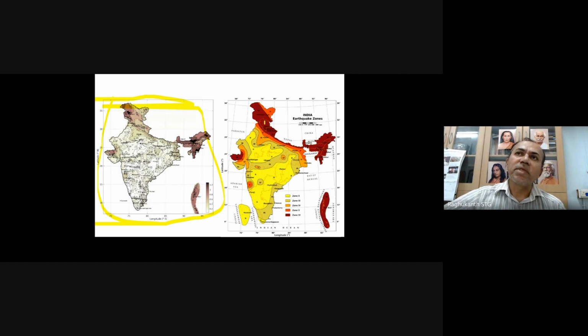Now, in the old zone maps, there used to be small islands. They were all coming from some damaging earthquake that has occurred; that island will come basically. So that has been removed from the contours itself, and this zone map has come up from the probabilistic, then deterministic, as well as the soil amplification analyses.